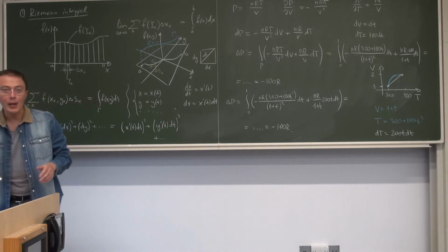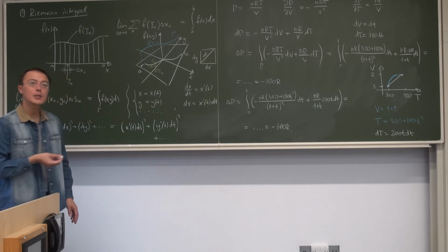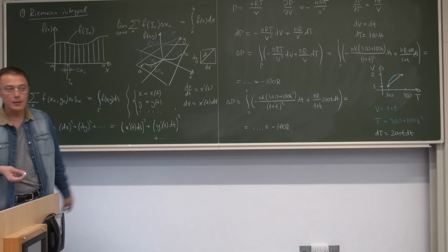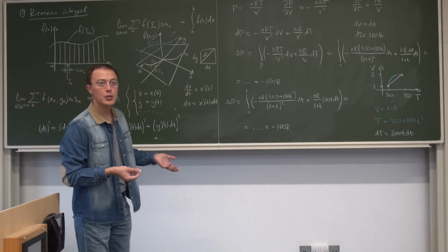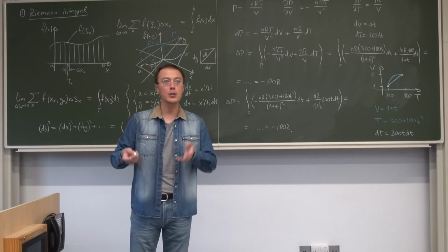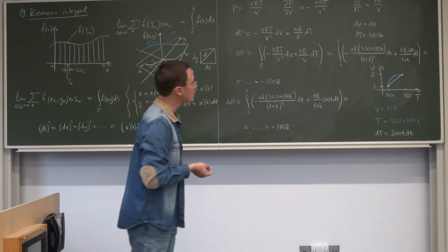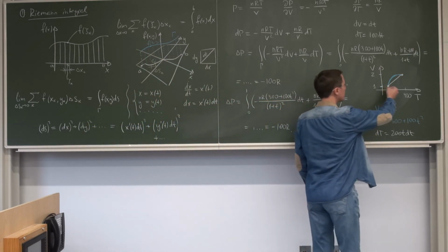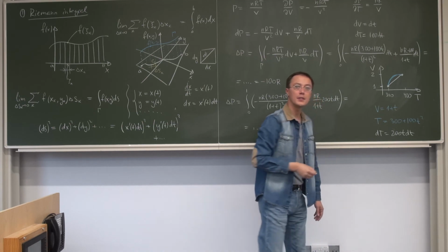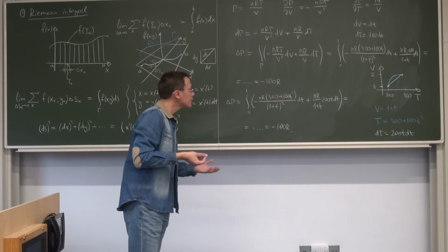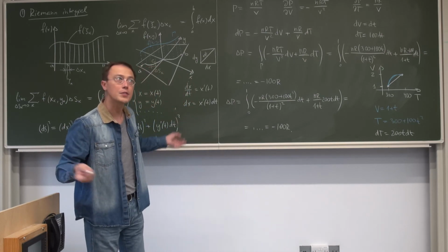You will see multiple functions in your thermodynamics course, notably work, for which this is not the case. And this is why some internal combustion engines are so much more efficient than others. That is because by designing the combustion engine, you are actually designing the path that your system takes in PVT space as combustion takes place, and then you can harness it better and harvest more of the energy at the output.